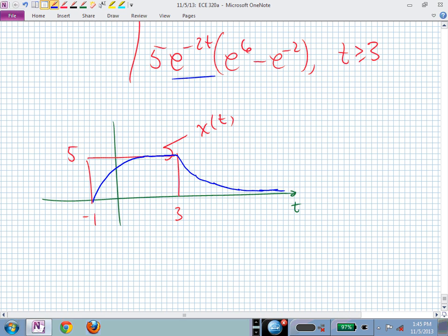That now looks kind of like a fin, a shark fin. But if we had a faster or a wider bandwidth on our filter, then we would have our blue line, our output, looking more and more like our red line, x of t. This is now our y of t, and if it was a much slower or very fine low-pass filter, we might not even get up to 5 before we turned off. And so y would be drastically different in behavior than the original waveform.